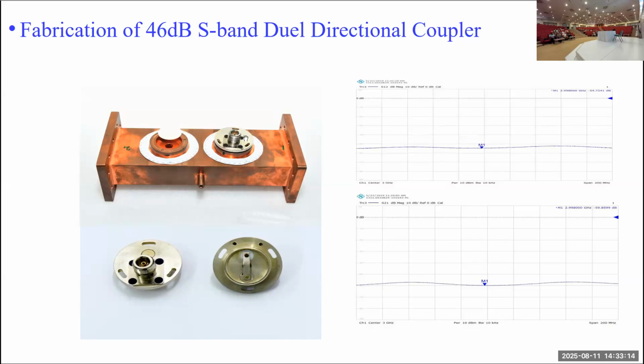The voltage, and the signal you measure at your power meter or your oscilloscope, will tell you how much power is passing or going forward. Definitely you have to include the attenuation of the cable you are using, and the attenuation of any other attenuator used to decrease the level of this signal must be added, and you will back calculate, and forward power is calculated.